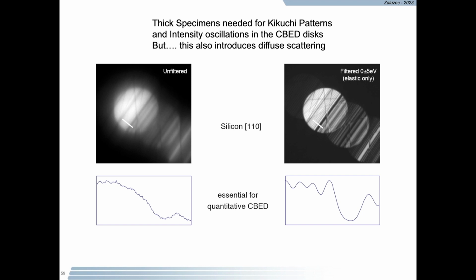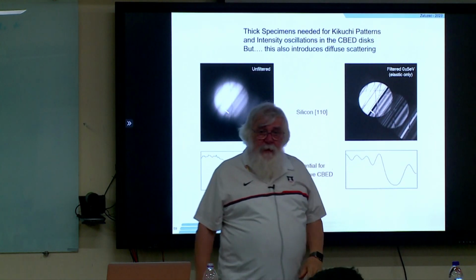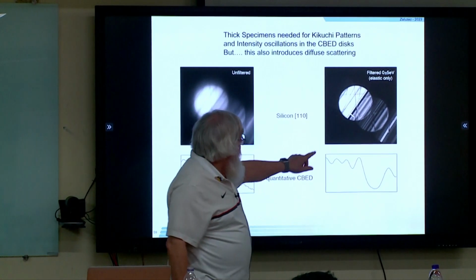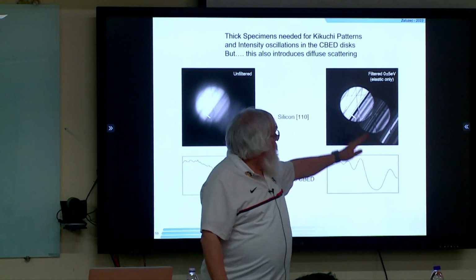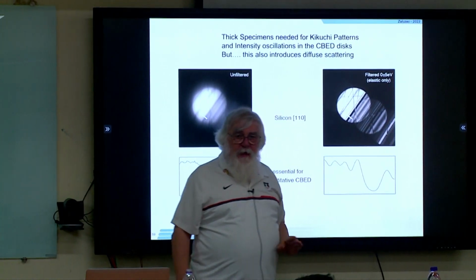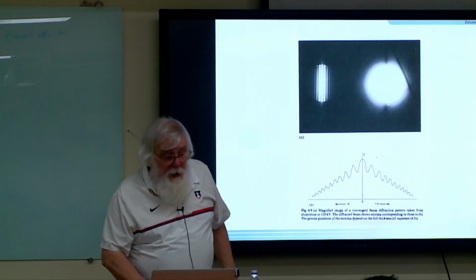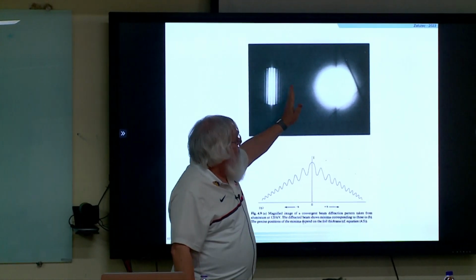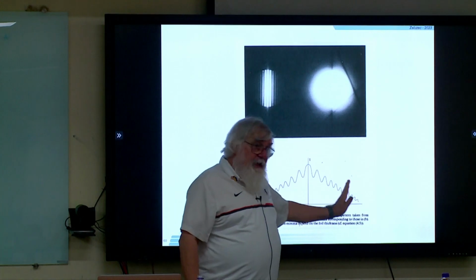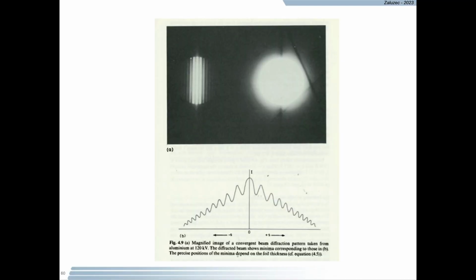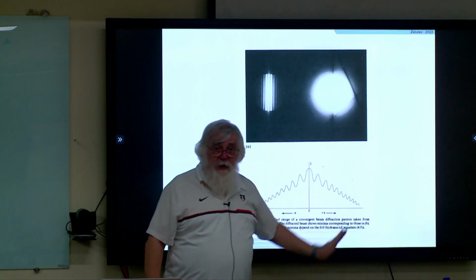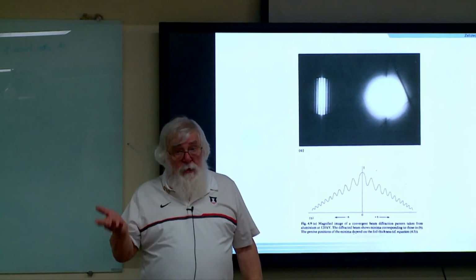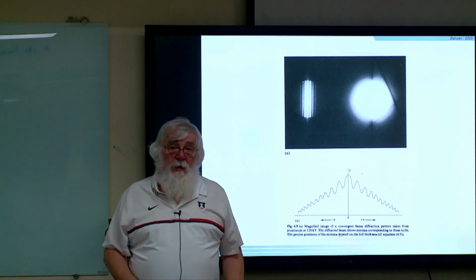I mentioned that structure in the diffraction and convergent beam patterns is very interesting. If I look very closely at this, this is now a diffraction pattern where I only have 2 reflections excited. Notice the periodicity in those lines. I can show you that periodicity, mathematically, is due to a change in the thickness of the solid. If I take a line scan through here, this is what I see. If I measure the periodicity of those fringes, and I know the material that I'm looking at, I know the lattice parameter, I can tell you how thick that sample is.